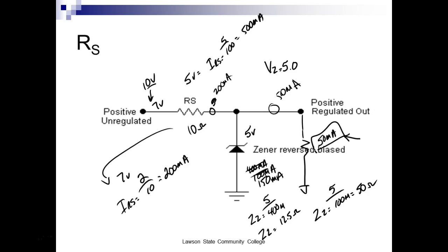So we can come up here. Let's say my load needs 150 milliamps at 7 volts. So what happens? My voltage is at 7 volts, right? You understand? 150 milliamps right here. I have 200 milliamps, so my Zener current goes to 50 milliamps. Do you have to touch anything? Do you have to do anything? No. So what happens is that your currents operate opposite. As your load current goes up, your Zener current goes down. If your load current goes down, your Zener current goes up, right?